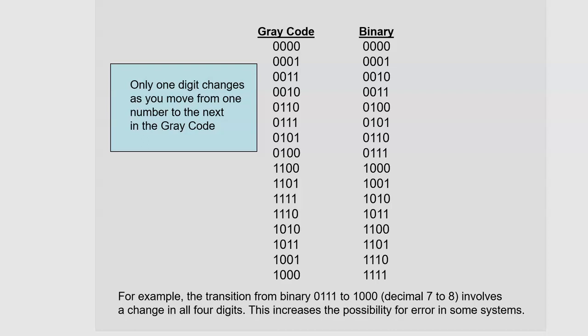And the way we're doing it in this class, if I have 5 volts, that's going to represent a 1. If I have 0 volts, that's going to represent a binary 0. So I can actually represent a binary number with the presence or absence of a voltage, either 5 volts or 0 volts. We can even move it around because I can turn those zeros and ones into a digital pulse, and we can move them around.